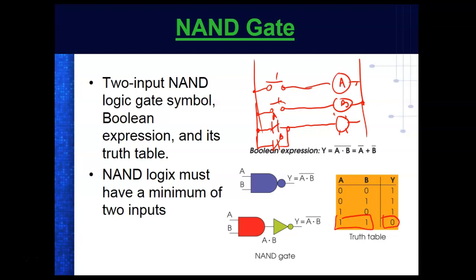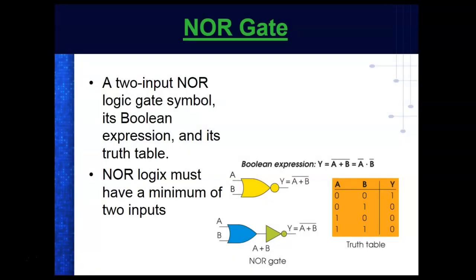This gets people messed up, because they come up here and see this, and we call this an OR. Now they've got that in their head, and they will come over here and see this, and they want to call that an OR. But it's not. So normally closed in parallel, this is a NAND, right? Everybody understand that? Okay, we'll see when I put that on the test. These are going to be on the next test, by the way.